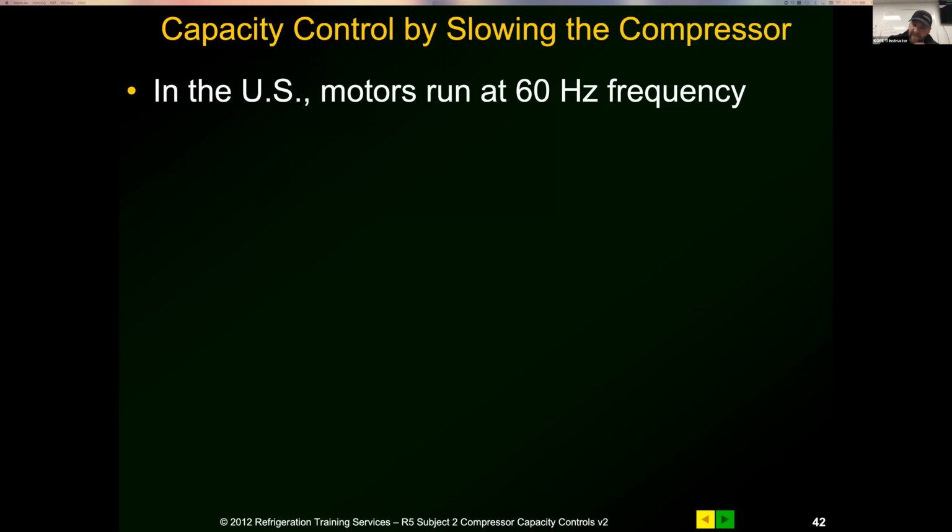So if you're sizing stuff up, make sure that you size to the same protocol type equipment. If you're using an Echelon, which is what Micro Thermal talks on, then you're going to want a drive that talks on Echelon. If you have a BACnet controller, you're going to want a drive that talks on BACnet. If you have a Modbus controller, you're going to want a drive that talks on Modbus. You just need to understand what protocol it talks, so that you know how to line up your equipment and get the best bang for your buck.